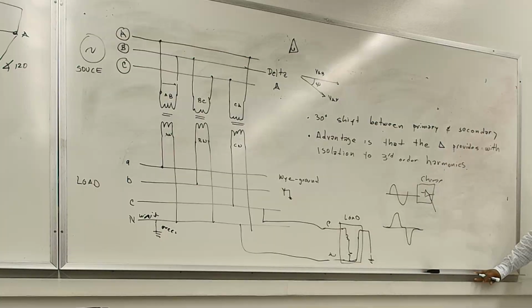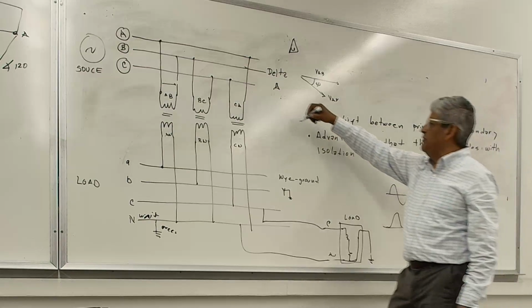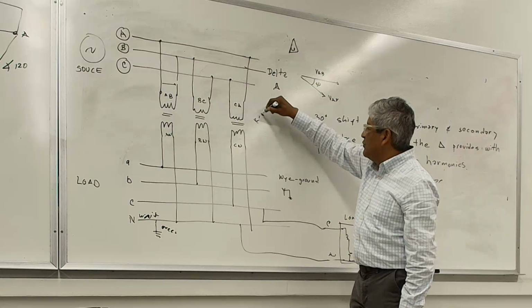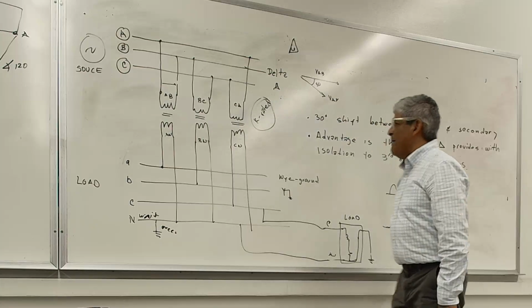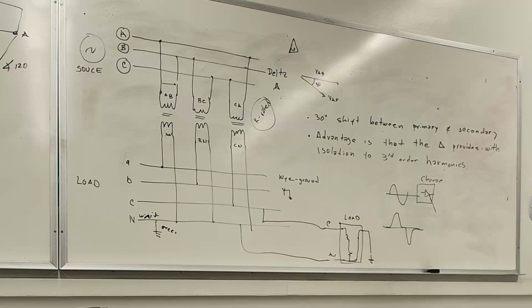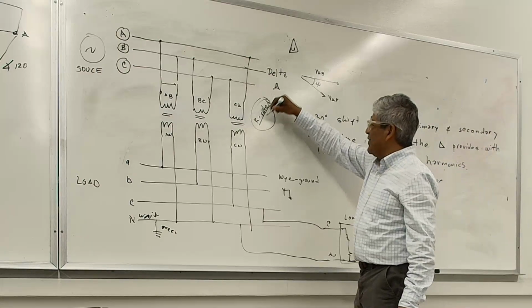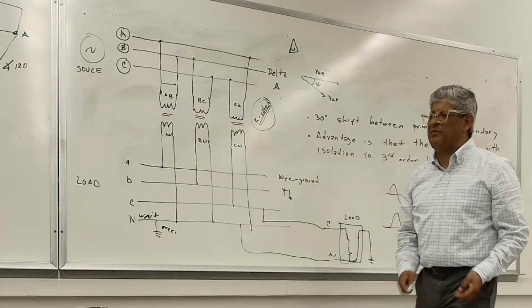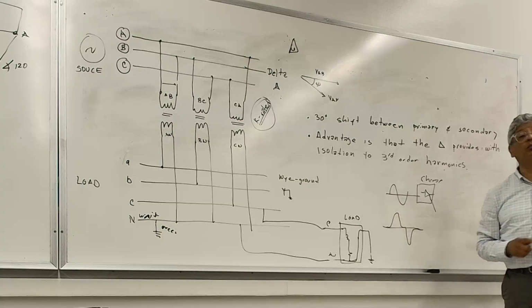You guys will hear it, not the utilities, but the industrial people, some of these transformers are called K-rated transformers. They will specify K-rated. The reason is they say, I want a transformer, say 12 kV on the primary to 240, 120 on the secondary, three phase, so 240, 480, 277 on the secondary for my loads. And I want that transformer to be K-rated. You'll hear that term, and a lot of times people don't even explain it. What is K-rated? Well, it can handle more energy.